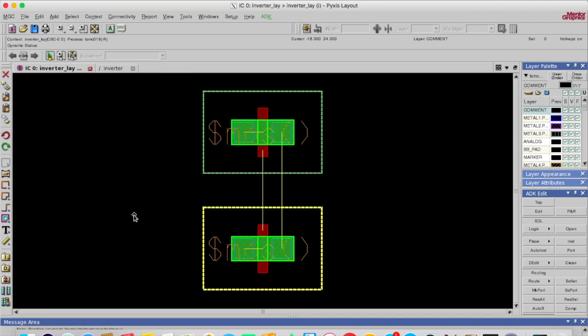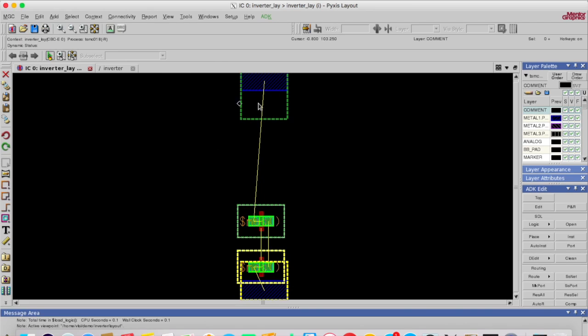For these things we have some instructions, some keywords. To generate power rails I'll press space bar, then PR. So these are power rails. I'll move these things down, so I'll select it. I would like to mention here, to select it you just click on this and it will get selected, and to unselect this you have to press F2.